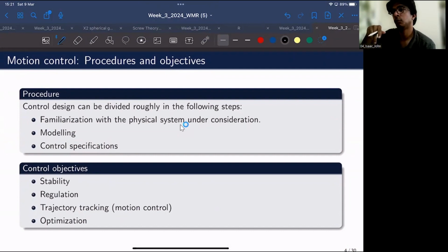Or maybe if you want to eliminate the overshoots and probably the oscillations, how should the damping be, how fast the control should react, how aggressive the PID parameters should be. All these things can be tuned, or should be tuned, based on the control specifications, depending on how the user would want the robot to behave.